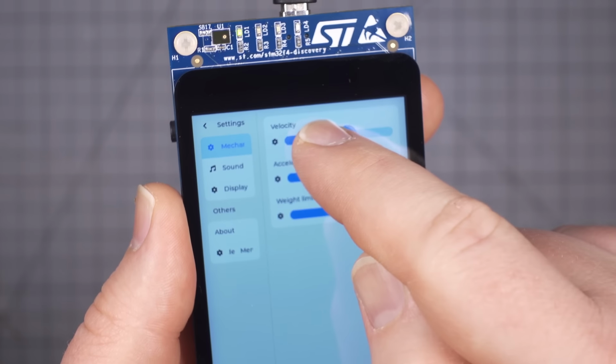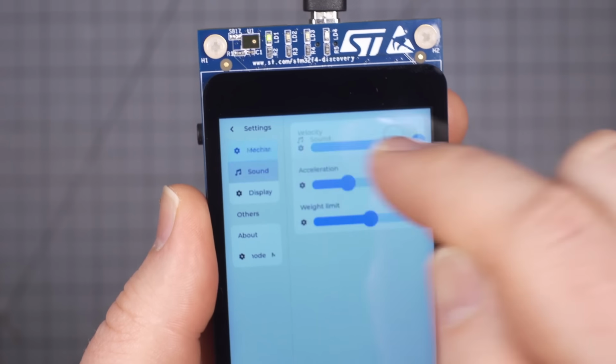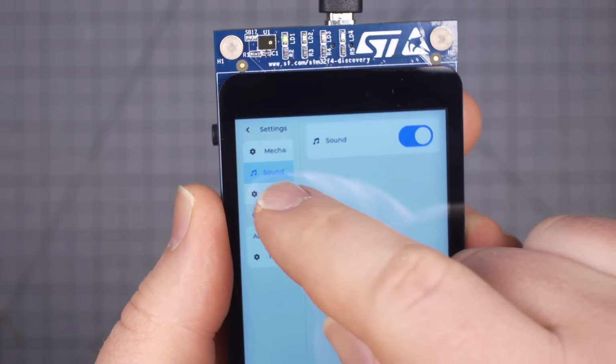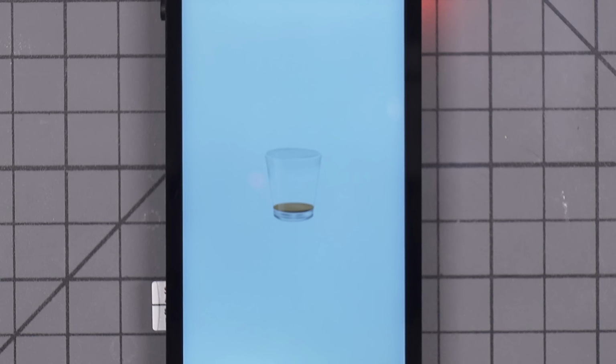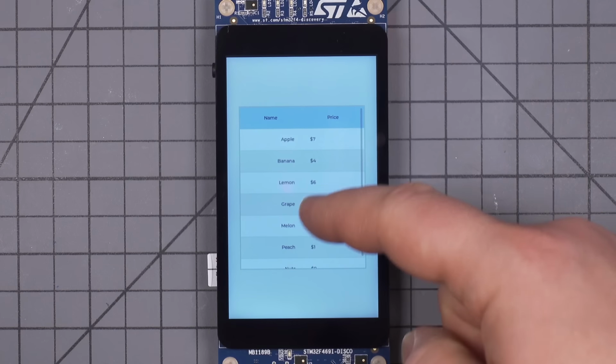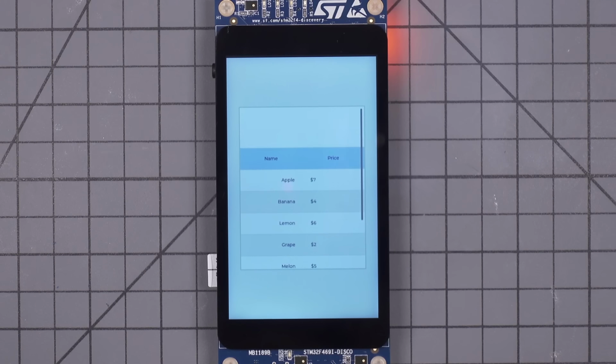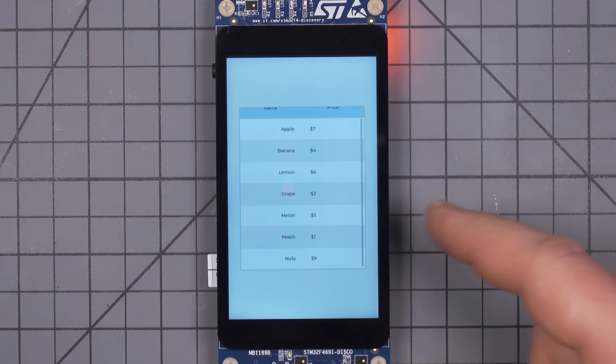These tools have a lot in common. The biggest thing they do is fill the frame buffer. What they fill it with and how they do that can vary widely, but common things are text boxes, buttons, menus, images, and widgets like sliders or gauges. These tools handle dynamic updating of the display, such as changing text in response to an input, repeatedly updating images to form an animation, or just refreshing buttons and lists in response to presses or slider movement.